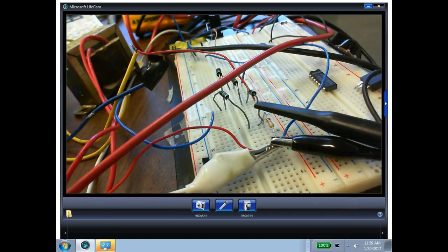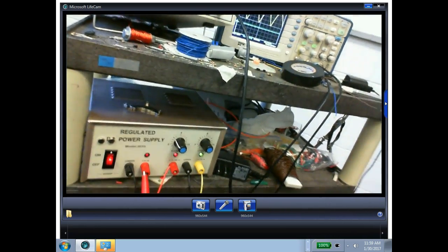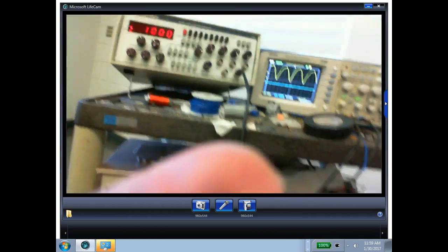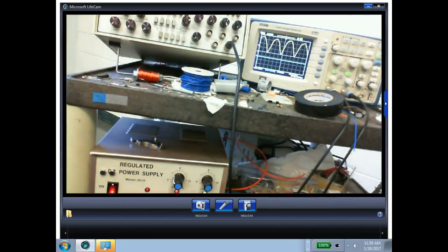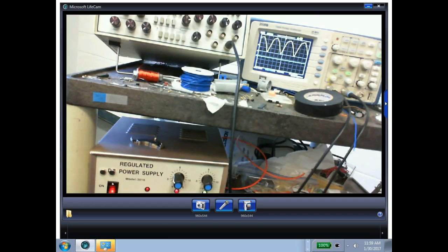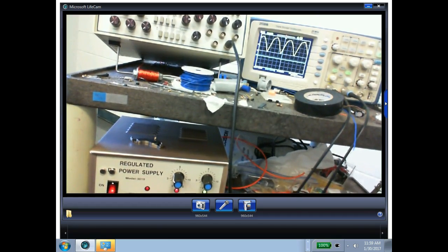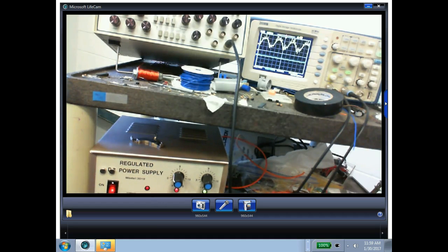Look at it with my oscilloscope. I have it hooked up already. There it is. I'm only looking at one channel. Can't use the other channel because we don't have a common. And there's my full wave. I'm going to hook up my motor. And now it takes off because it's getting 10 volts instead of 5 volts, right? Nice and smooth.